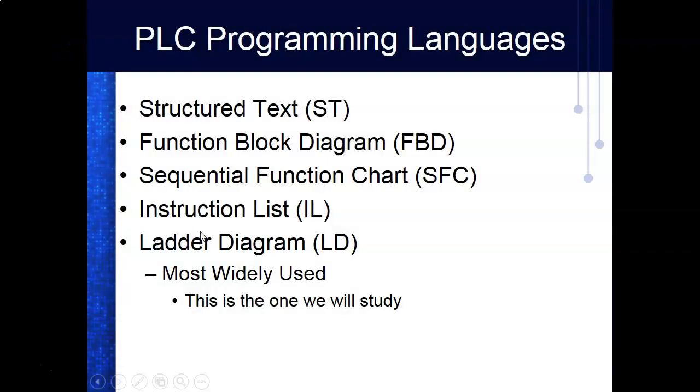So for PLC programming, these are the five languages available. I'm just going to show you an example. Structured text, referred to as ST; function block diagram, which is FBD; sequential function chart, referred to as SFC; instruction list; and ladder diagram, which is LD, by the way. This is the most widely used in the world, and it's definitely the most widely used in the United States. So this is what we teach here.